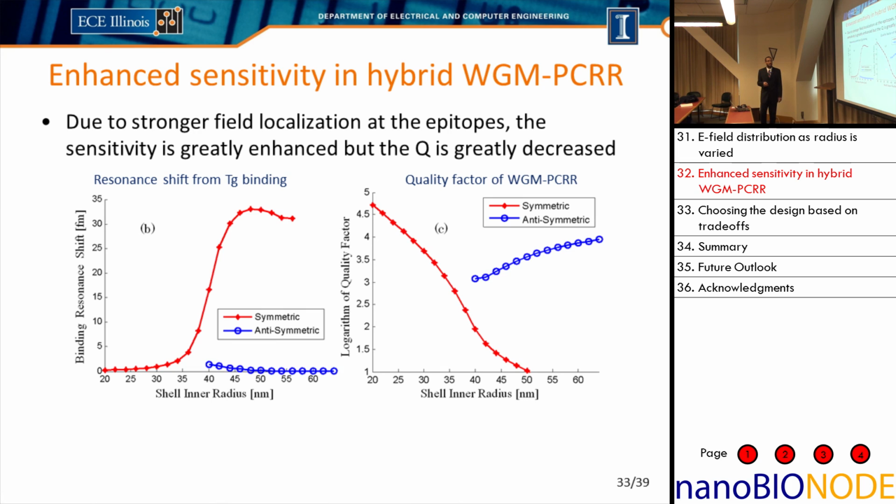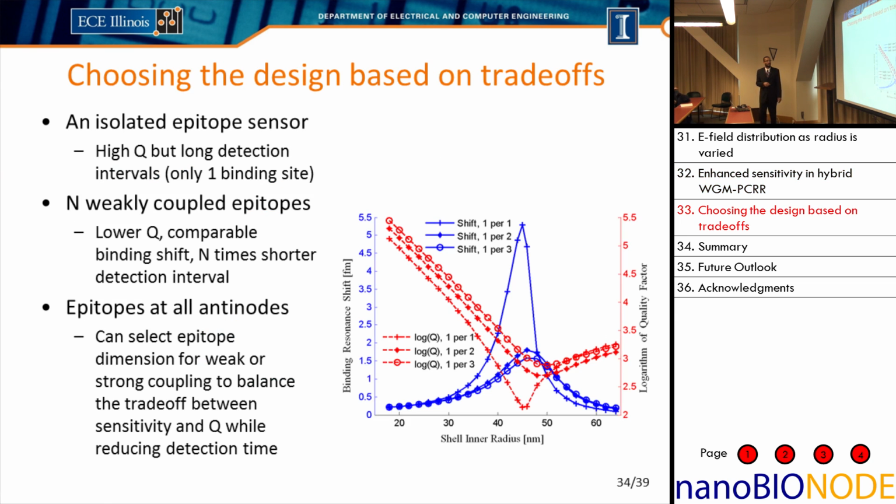And as a result, it becomes difficult to measure the small shift. So there may be an optimal point in here, depending on the instrumentation that you have, whether you're limited in terms of the measurement accuracy of the tunable lasers, where you can trade off a larger resonance shift for having a wider resonance, or you can have a smaller resonance shift for having a narrower resonance.